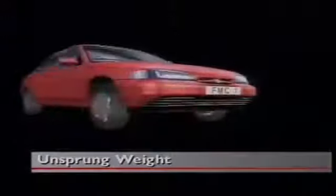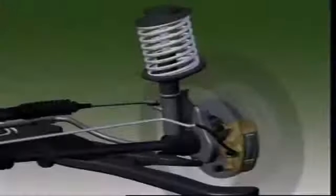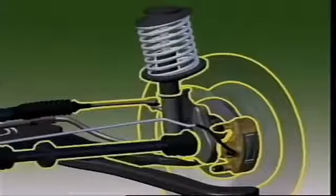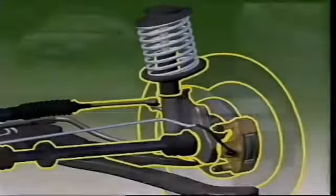Most of a vehicle's weight is supported by its suspension system. It suspends the body and associated parts so that they are insulated from road shocks and vibrations that would otherwise be transmitted to the passengers and the vehicle itself. However, other parts of a vehicle are not supported by the suspension system, such as the wheels, tires, brakes, and steering and suspension parts not supported by springs. These parts are all called unsprung weight. Generally, unsprung weight should be kept as low as possible.